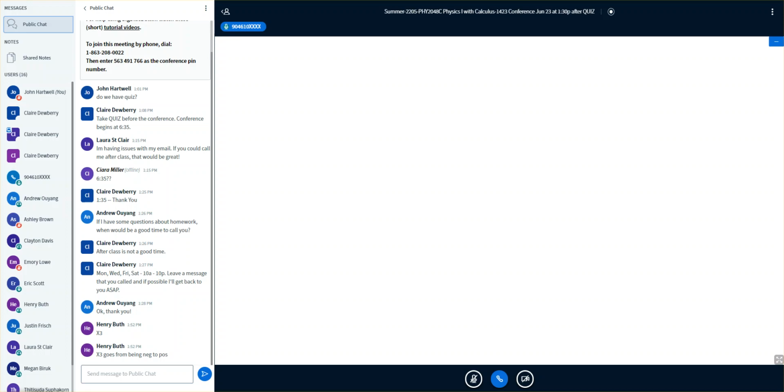Fitting that into the work energy equation in the upper left-hand corner, you'll get the following expressions very much like mine. And instead solving for the cosine, and it's interesting that you will have a tangential effect. You'll have sine over cosine for your mu value. And I wish we were doing a lab on friction because this reinforces the tangent of the angle as it's moving is an indication of its coefficient of friction, providing that's the only thing acting, friction, while it's moving.